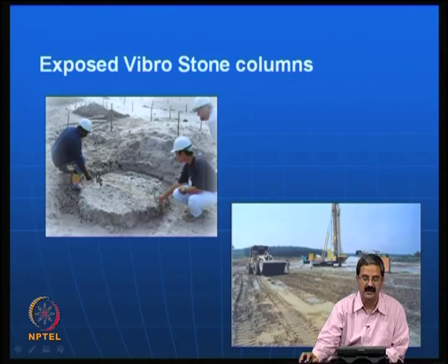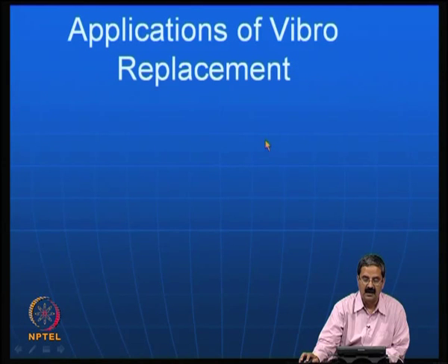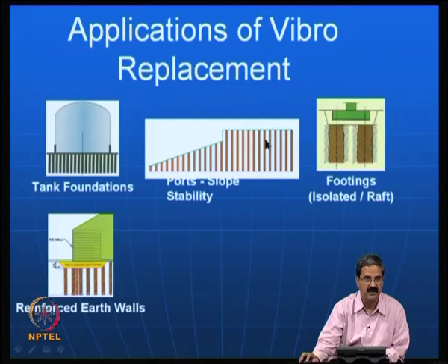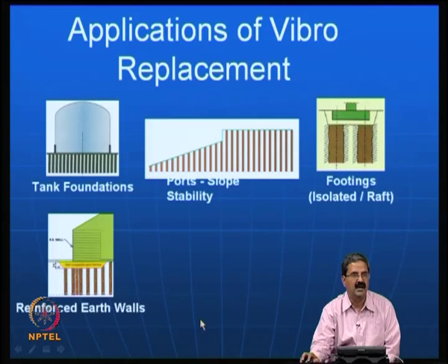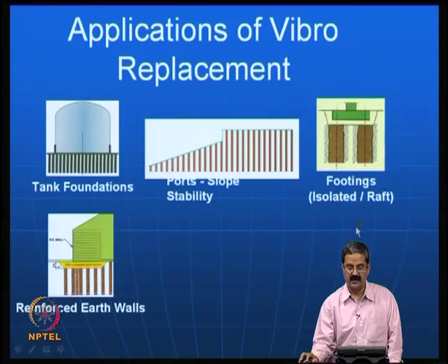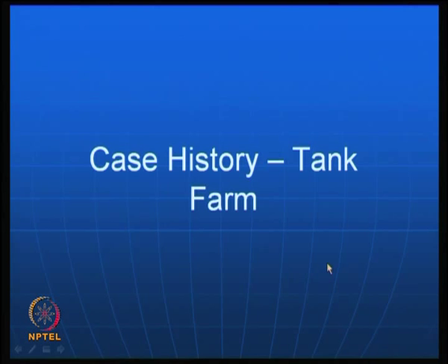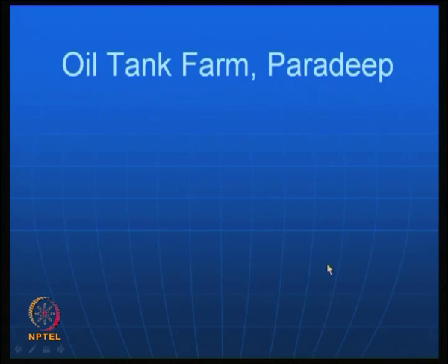If you want to really see the diameter, you should be able to do that quality control, measure the diameter. It has been very well used in many applications like tank foundations, particularly in soft soils, ports, and slope stability, as I just mentioned, is another important issue. Reinforced earth walls, actually in some places where the bearing capacity of the reinforced soil wall is very poor, you need to have foundations like this. Then isolated footings also it can be done, railways people have done, highway embankments people have done. So, we will just see some of the case studies they have provided to us.